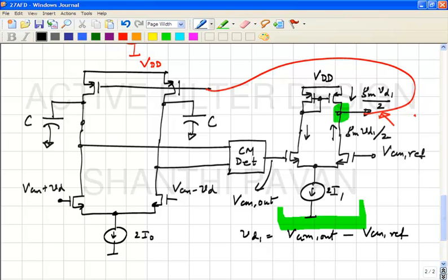So when we are dealing with stability, we better put down all the capacitors that we are likely to encounter during operation, correct. The first thing is, of course, the intentional capacitance that you put to perform the integration operation. The integration operation is happening only for the differential mode half circuit.